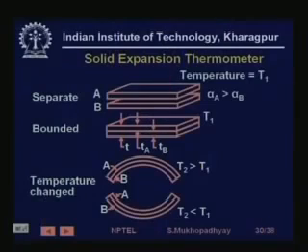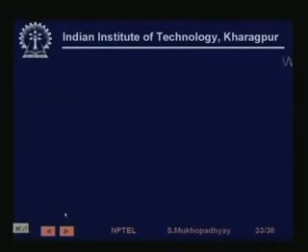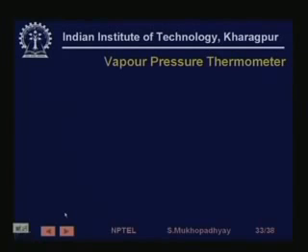If temperature decreases, it will turn one way. If temperature increases, it will turn the other way, right? So therefore, from this motion, we can measure temperature. And there are industrial sensors which actually utilize this kind of bimetallic sensor. They are sometimes also used for temperature switches, and sometimes they are used as bimetallic springs. So as the temperature rises, the spring rotates, and it can be connected to something like a dial.